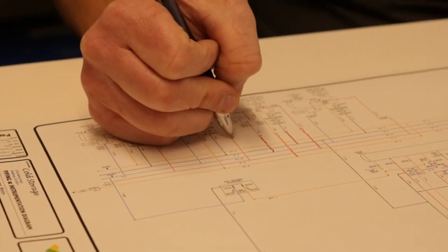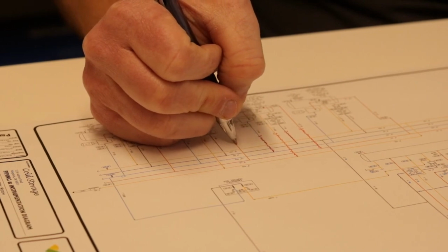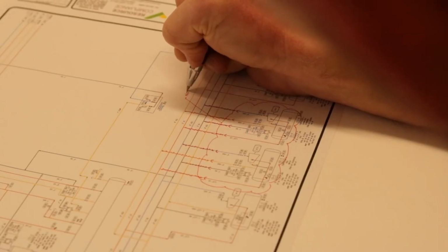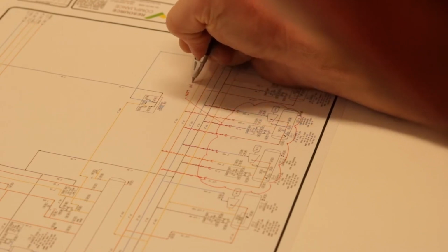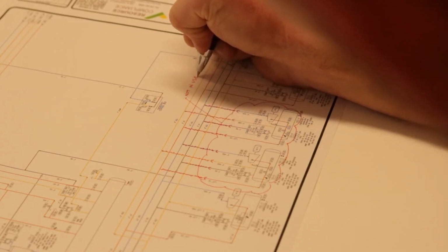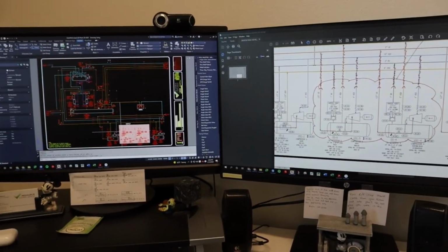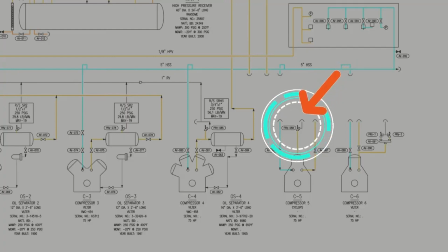Prior to implementing changes, it may be prudent to redline the existing P&IDs by hand with a red pen. This method of depicting alterations is particularly effective for smaller changes to process piping and equipment. After the project is completed, the redline P&IDs should be audited so that the as-built drawings can be finalized using AutoCAD.